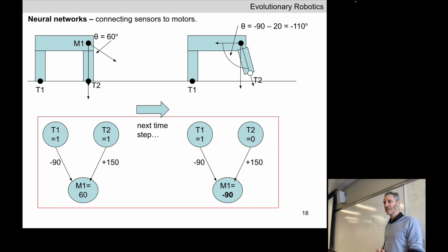Could add another link that can go up and down. We could add another link that could go up and down. I've run out of space here, so let's just stick with 3 links and let's just change one of the joints. So we're going to keep this one rotating link 0 and 1 horizontally to one another, but we want to change this joint normal so that link 1 and 2 are now going to rotate through the vertical plane, through the YZ plane.